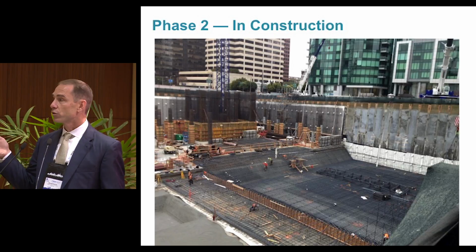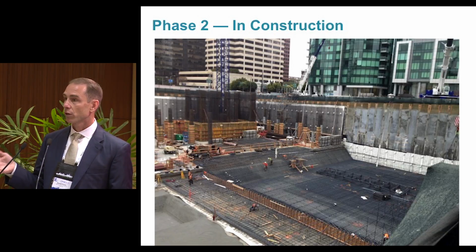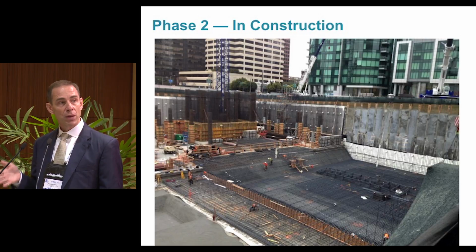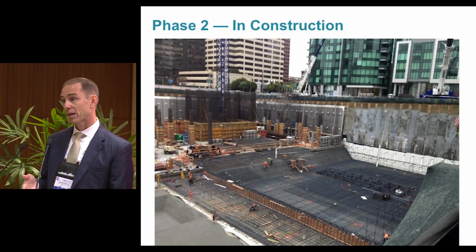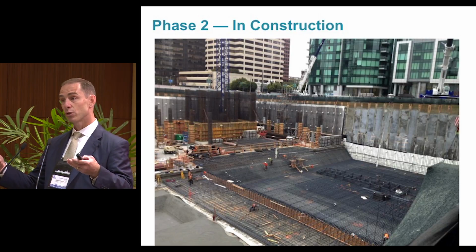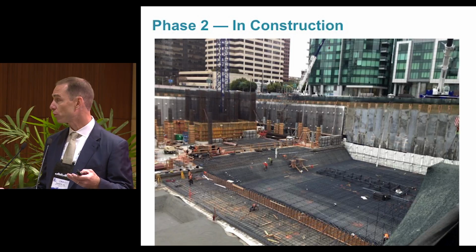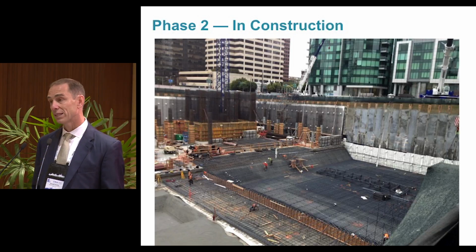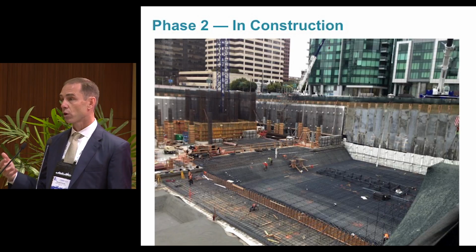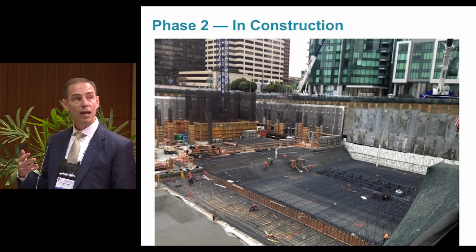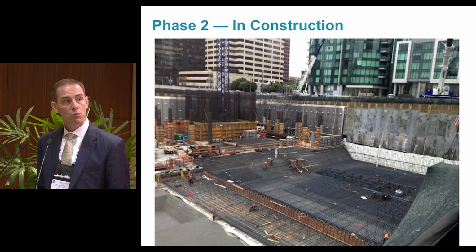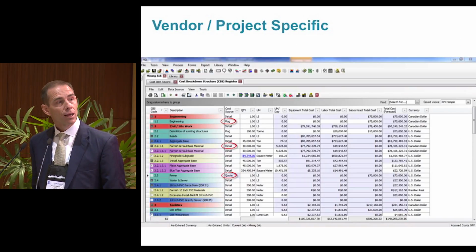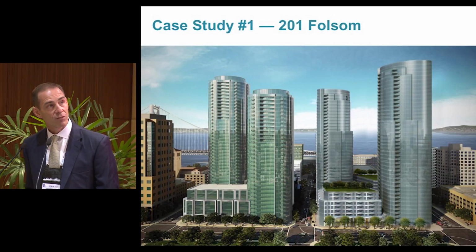And then I mentioned construction. I think doing that model during design is great, but it is really only based on industry average information. The best way for us to affect change is actually at the point of the buying decision and to bring environmental impacts into that buying decision. So maybe for a material like concrete, if the costs are the same between two different suppliers, but one has a much lower embodied carbon footprint on the material, that should be the one that leads the day. And I think that's one of the values of trying to use this LCA tool and, frankly, EPDs, which I'm talking about. If the market pressures are there to request those, you can start to use that in your process. You get that in, like I said, you can get the vendor-specific information.